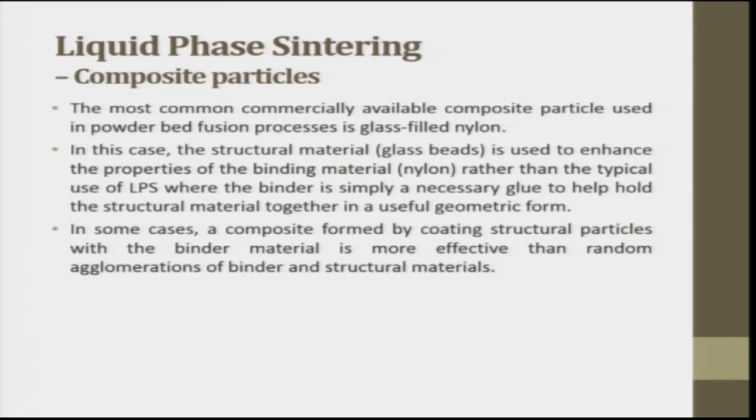The most common commercially available composite particles used in powder bed fusion process is glass filled nylon. Glass filled nylon. In this case, the structural material glass beads is used to enhance the property of the binding material nylon rather than the typical use of LPS, where the binder is simply a necessary glue to help hold the structural material together in a useful geometric form.